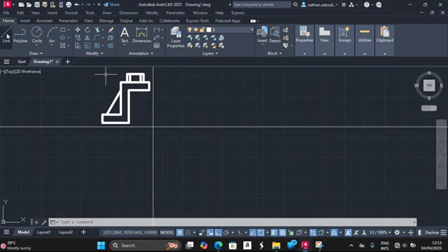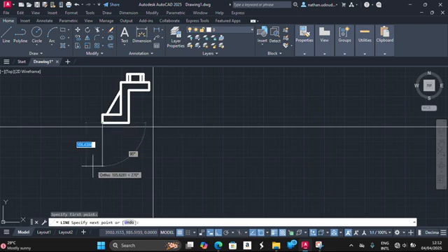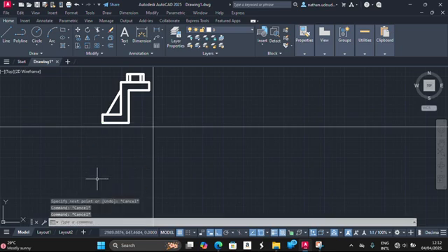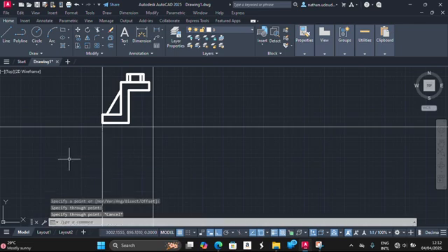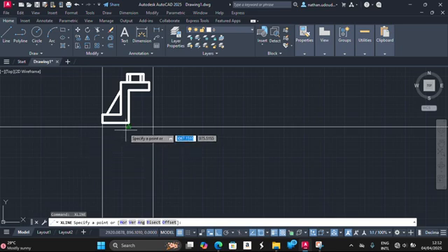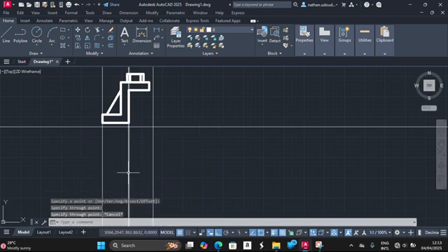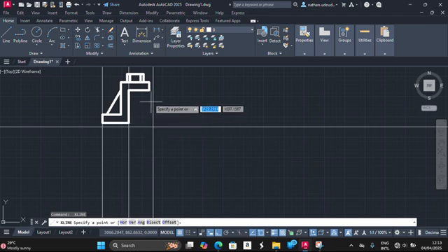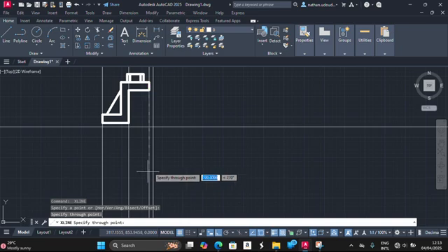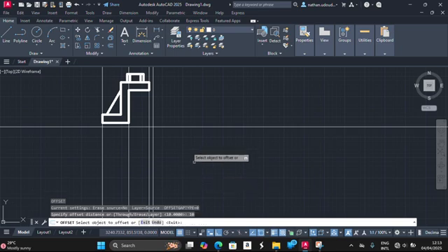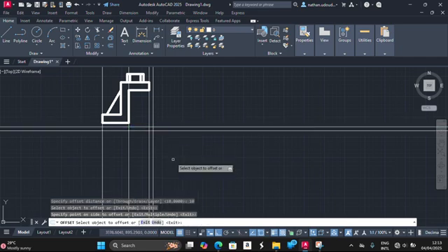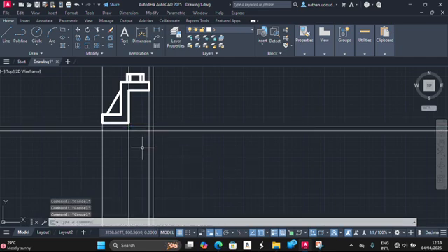So now you pick up your line command from this point, or you can use your construction line XL, enter, like that, spacebar to repeat the previous command like that, spacebar again like that, and then coming down that way. So now you can take your offset line, 10, 1, 0. So you offset this. So of course, that's where your plan is going to start. It's going to be starting from somewhere here.